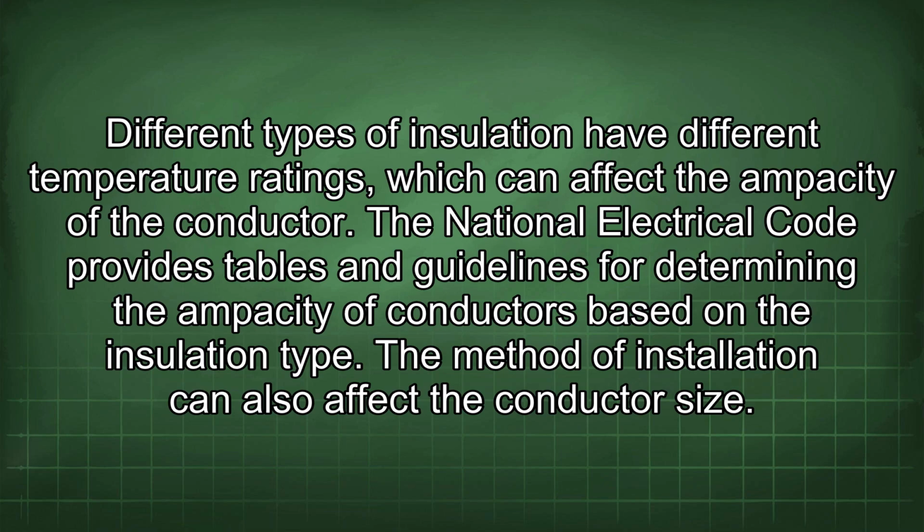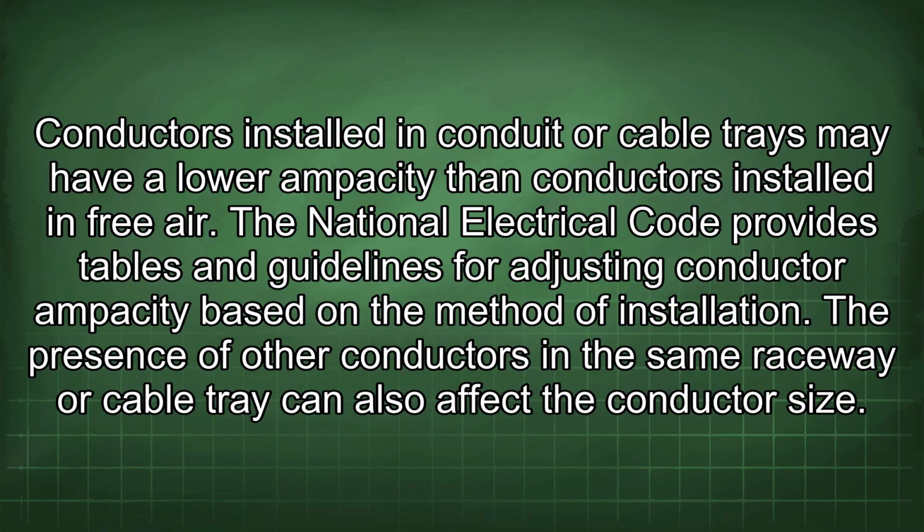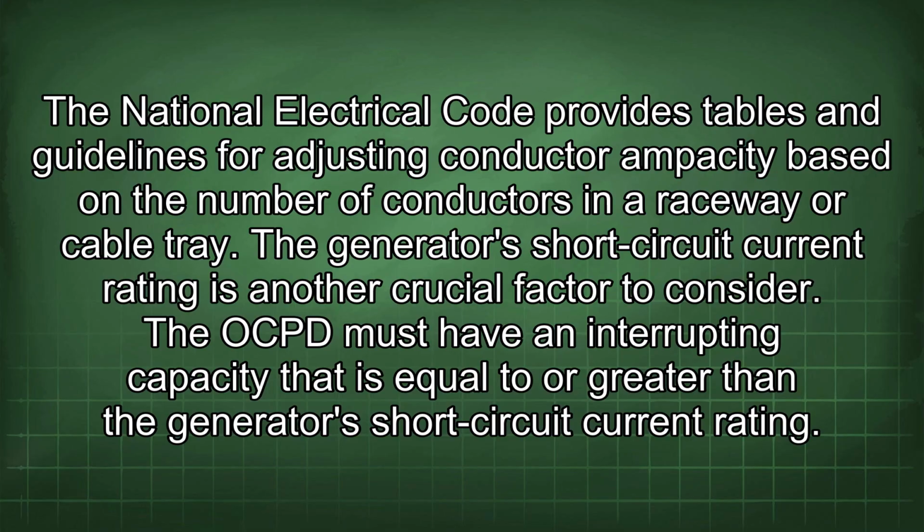The method of installation can also affect the conductor size. Conductors installed in conduit or cable trays may have a lower ampacity than conductors installed in free air. The National Electrical Code provides tables and guidelines for adjusting conductor ampacity based on the method of installation. The presence of other conductors in the same raceway or cable tray can also affect the conductor size. The National Electrical Code provides tables and guidelines for adjusting conductor ampacity based on the number of conductors in a raceway or cable tray.